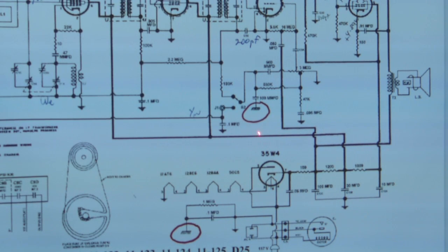You'll also notice that here on the power input, there's a 1 meg resistor with a 0.1 cap in parallel with it. Up here, there's just a single, very low value cap. It's probably a mica, probably a ceramic, that's connected to the chassis ground. So those are the only 2 chassis grounds in this circuit. Let me ask you the question: why are these there?